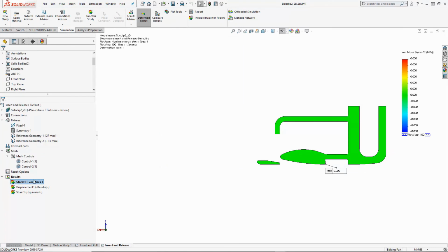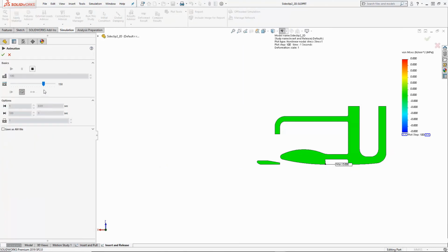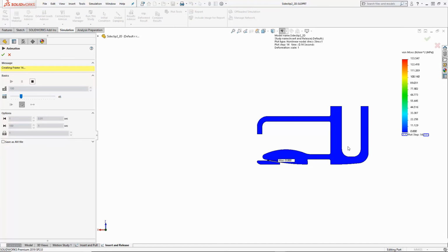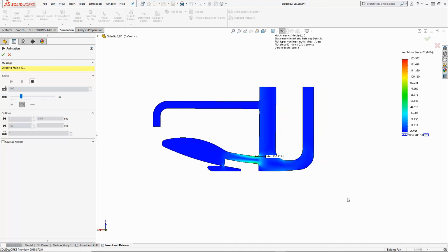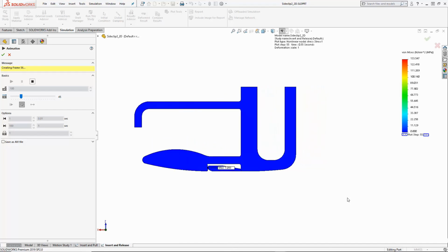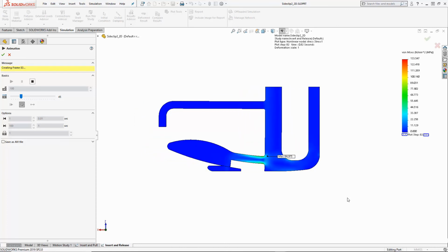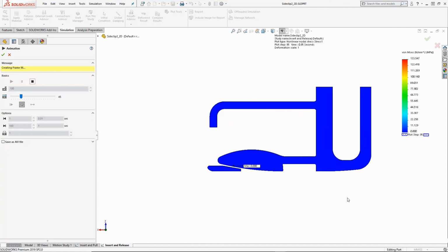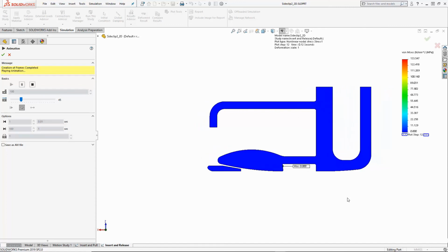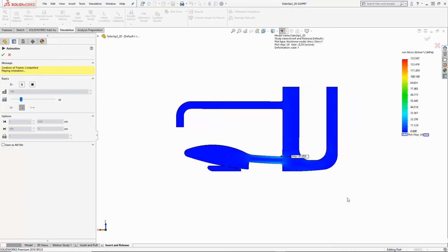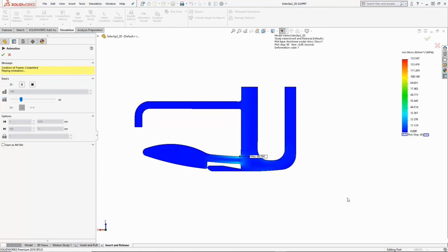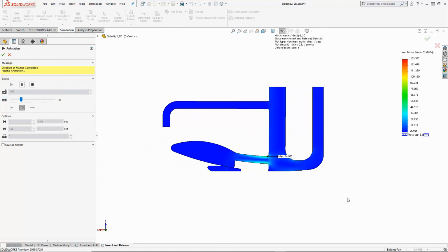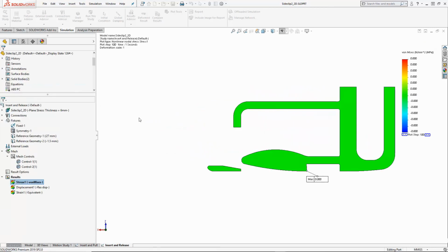So this is 2-dimensional. It runs pretty quickly. Again, I can watch intermittent results, but I just want to show you the animation here so you can see how my different fixtures have affected things. This is definitely a nonlinear contact. We certainly have a large amount of motion. It would probably trigger a large displacement flag if we ran this other ways because of how far it's moving. But I also have this ability to turn on and off loads and on and off fixtures over time and deal with this more complicated contact until there's a lot of friction there, there's a lot of things changing, and then all of a sudden it quickly releases. Using a pseudo time curve and a nonlinear solver gives us the ability to manage that.